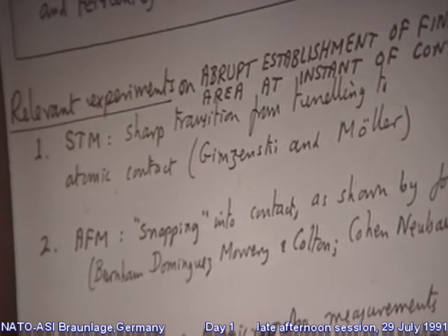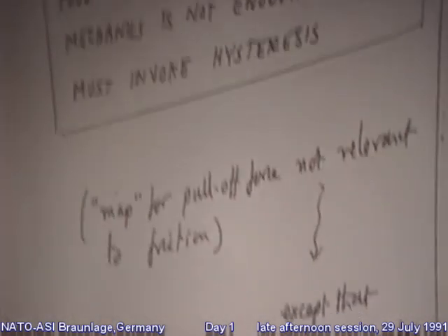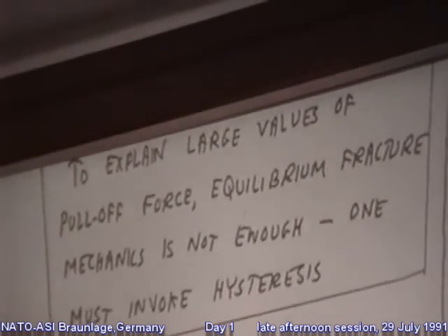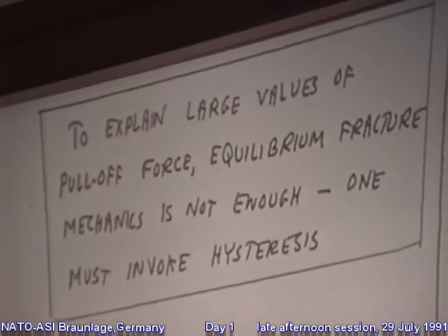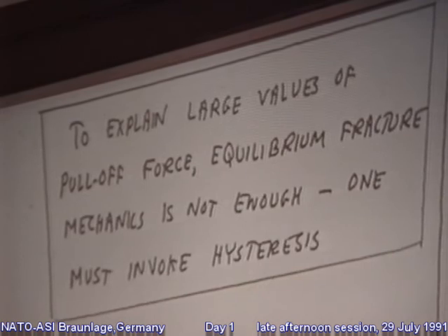Right, the last major topic that I want to mention is this one, because there is an important concept in friction that is more or less exactly parallel to this one. And that is, the pull-off force we get in practice, in many cases, is very much larger than what we would get from equilibrium fracture mechanics.